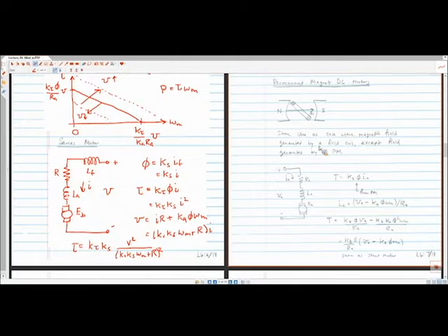Does the permanent magnet in the motor lose its magnetic property over time? It seems like you're getting a free field, like it takes energy to make the field in the other motors we talked about, and here you just get a free field permanently. It's like a free lunch, right? Yes, it will lose it over time, especially as it's sensitive to thermal cycling, and you can also actually demagnetize it. So I would say that it's not necessarily free.